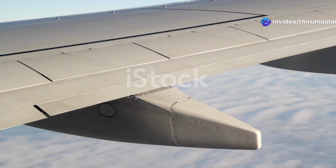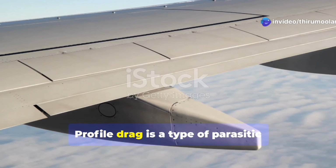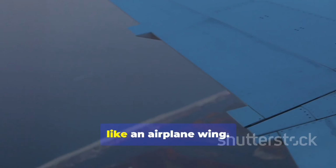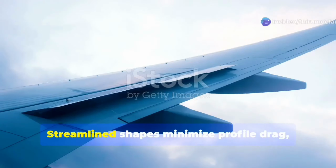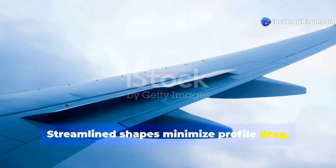Profile drag is a type of parasitic drag related to the shape of an object moving through the fluid. It's like an airplane wing. It combines form drag and skin drag. A streamlined shape minimizes the profile drag, while a blunt shape increases it.